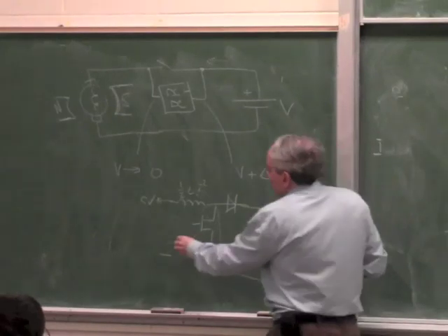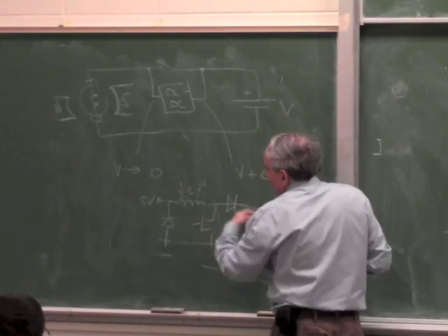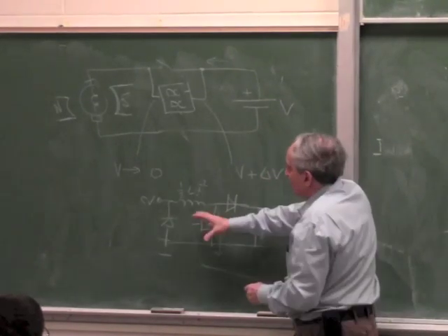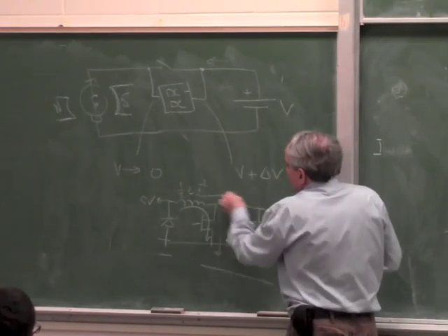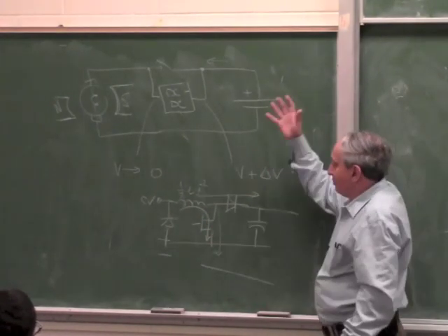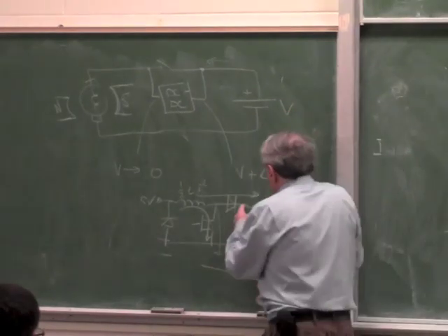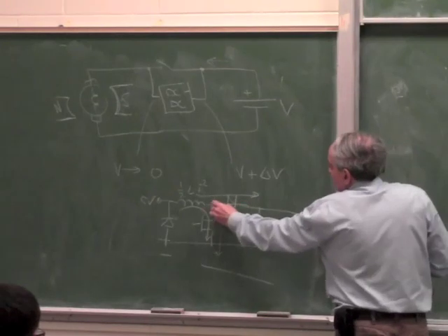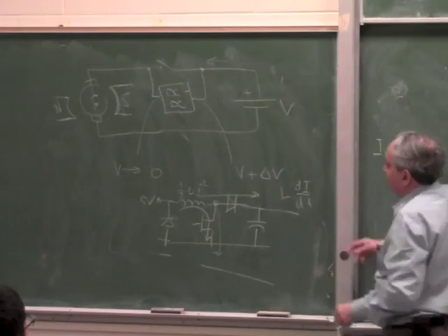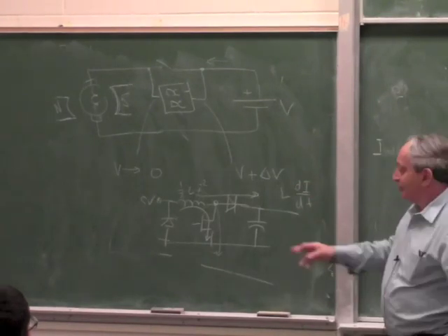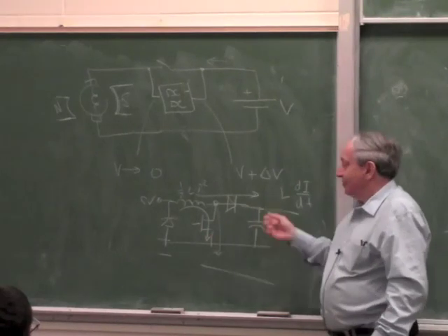Okay? And you put another diode here. The purpose of this diode is to close the loop this way. So each time you open the switch, when you close the switch, the current flows this way. When you open the switch, the current flows this way, but it wants to jump to infinity. The voltage wants to jump to infinity because, as I said so many times, the voltage here is L di/dt, and you can make di/dt as small as possible. And by playing around with this pulsing, you can correct the voltage here.